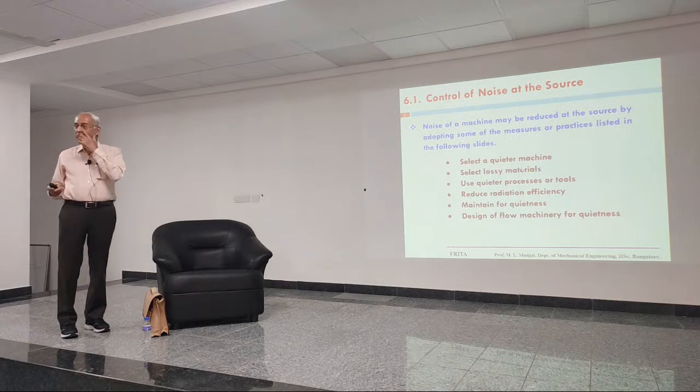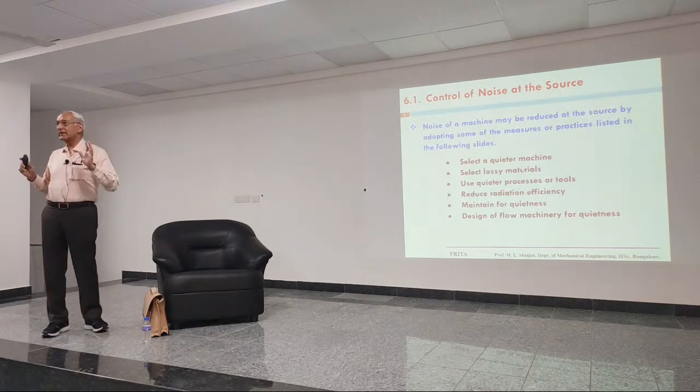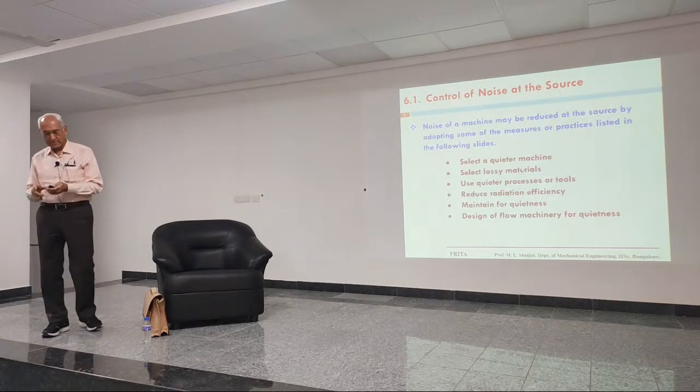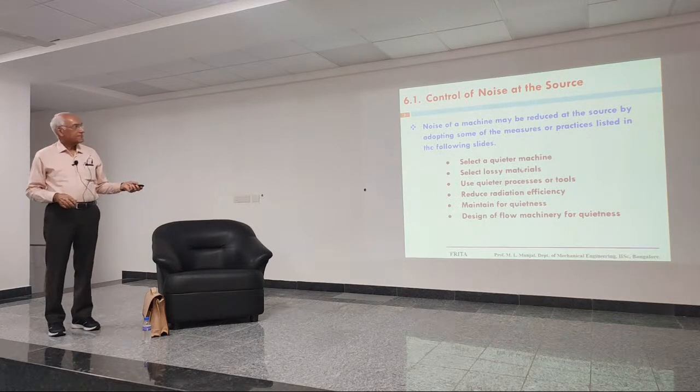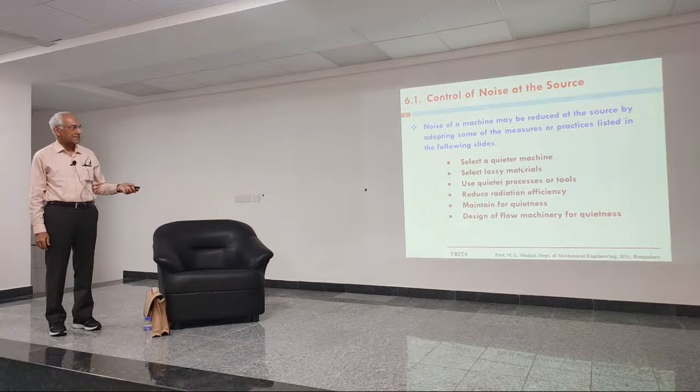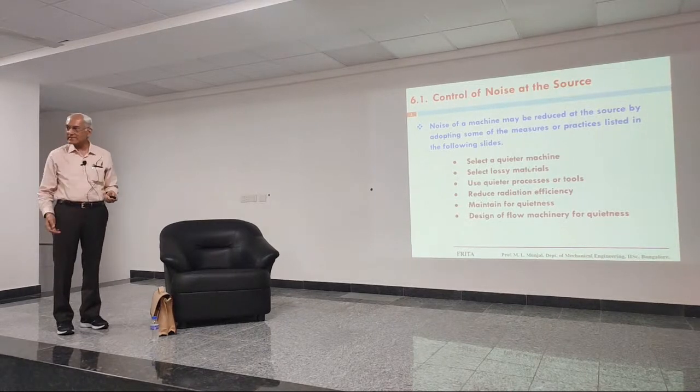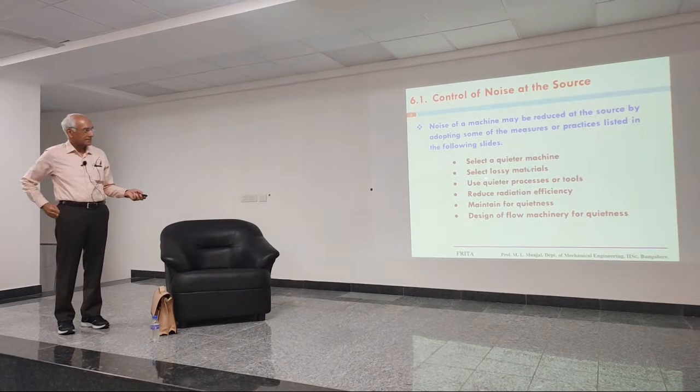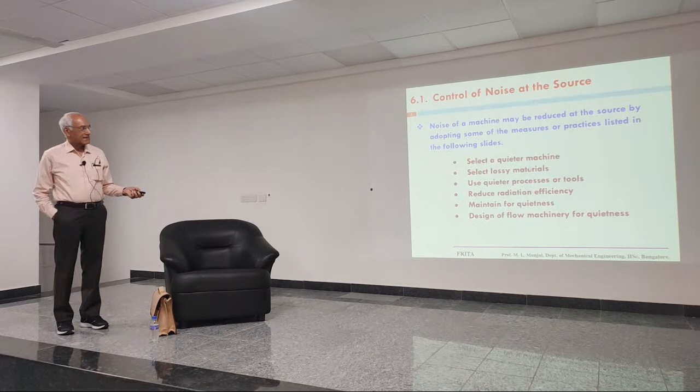Now, as I told you, the first thing I should ask myself is, can I control the noise at the source? Noise of the machine may be reduced at the source by adopting some of the measures or practices listed in the following slides. These are the titles of the next slides that are coming, but I will just read you the titles. First is select a quieter machine.